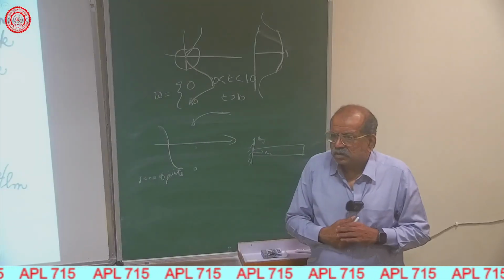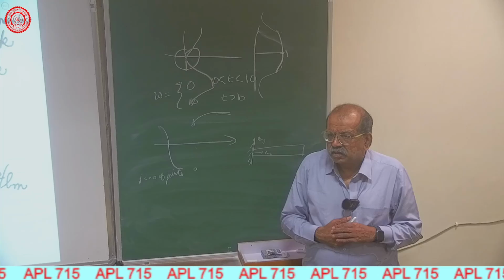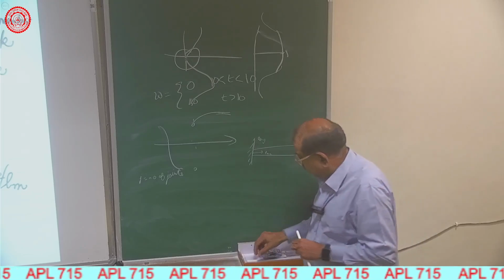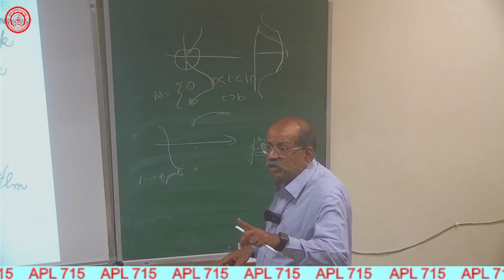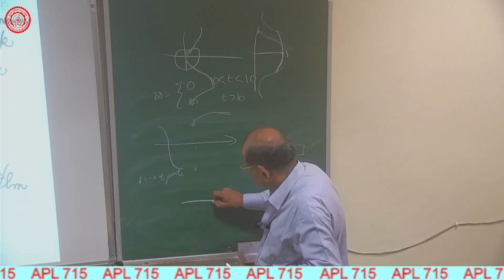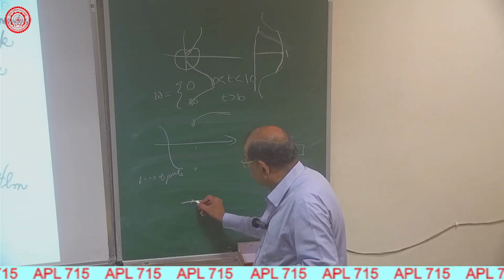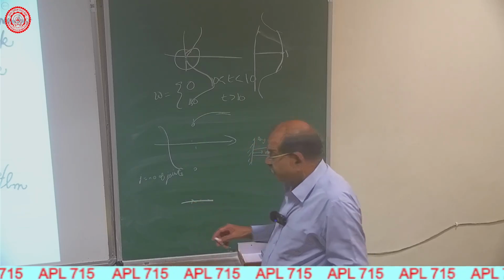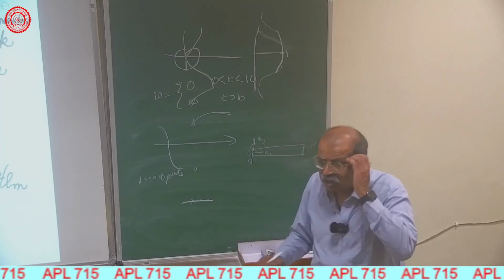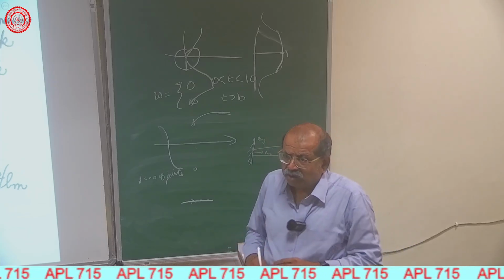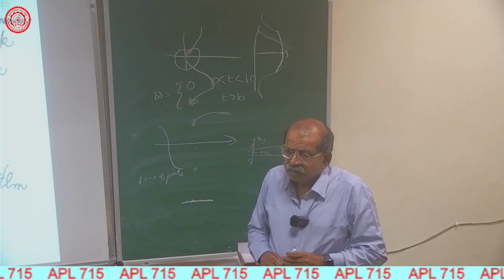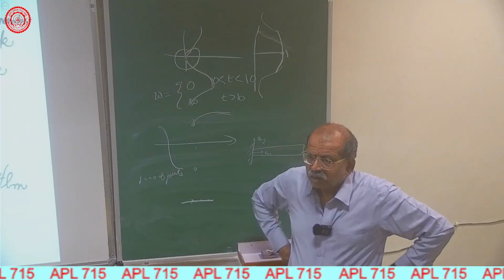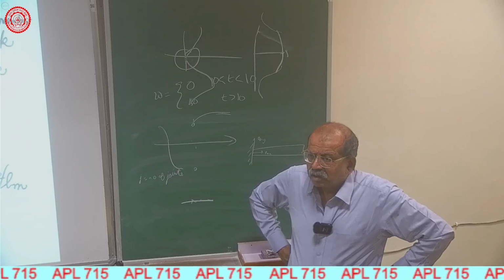In the no slip condition, does it also take care of perpendicular to the boundary? The no slip tells you, so derivative will not be zero perpendicular to the boundary, but the no slip takes care of the total velocity vector being zero. So even Reynolds stresses will be zero on a solid boundary. But particles can just ram into the wall and go back, right?